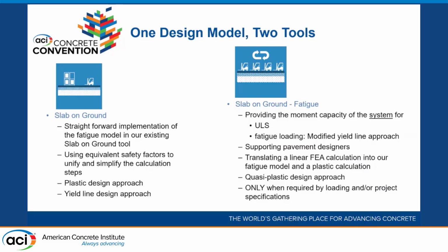So we recognize that the FEA models we have access to don't have the ability to track cracking and to modify the loading as the moment of inertia changes with cracking. This is something that we want to move into, but as it is right now, it's the more simplified yield line approach that uses a modified load factor approach.